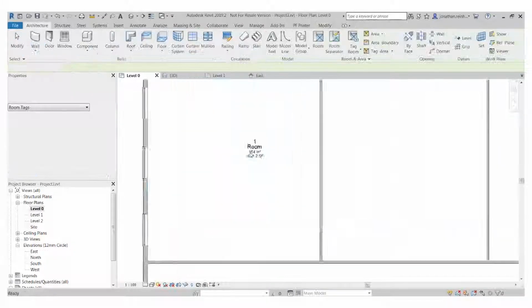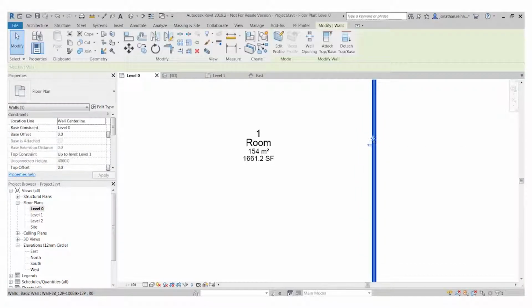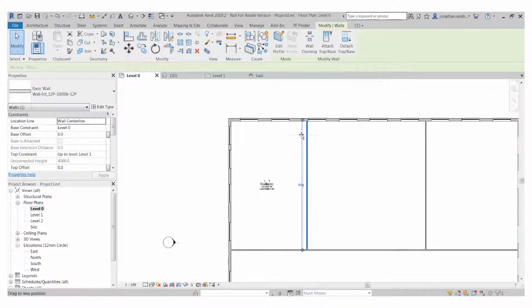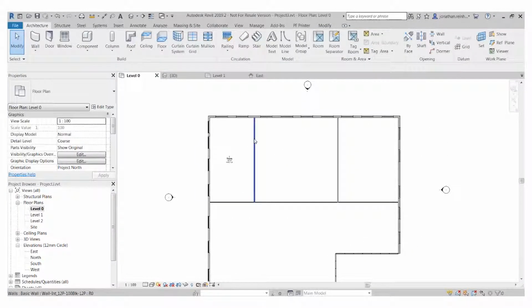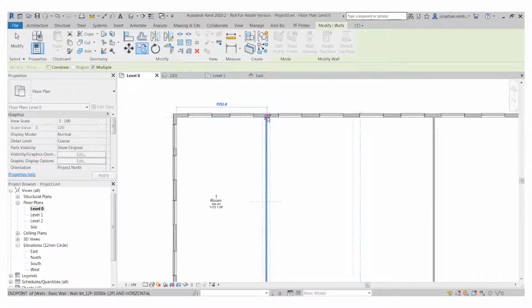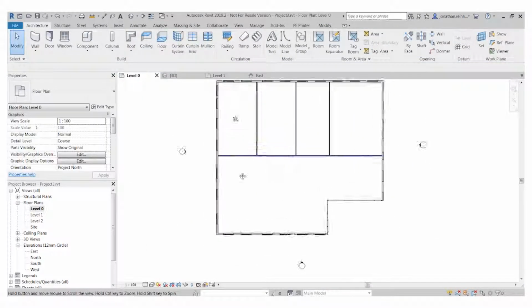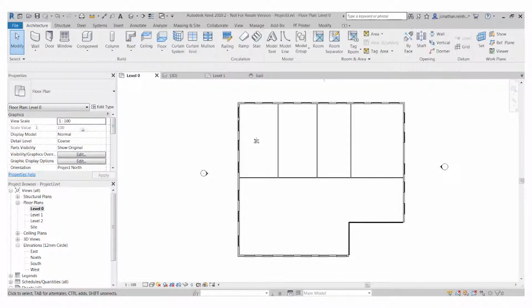Just going to hover over that, and that's going to bring up the square meter of that. If I then move this wall, for example, you can see that square meter has updated automatically as well. Obviously I don't want it on the wall join. I'm just going to place that there. I'm just going to start copying this wall across at kind of equal distance to what we already have set out. So there, that was already done. So we can zoom. I'll leave that one as kind of a bigger size, and I'll show you about placing this onto sheets in a moment as well.